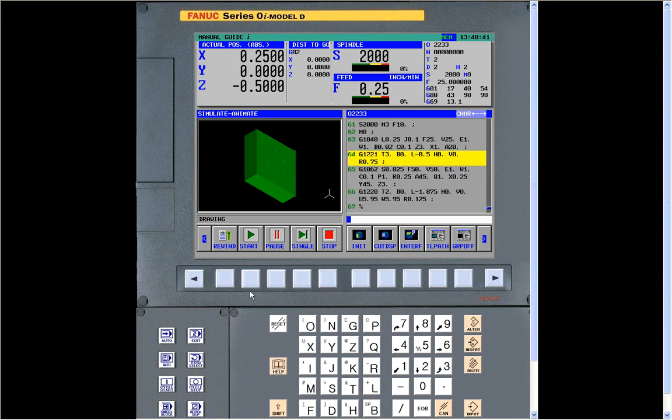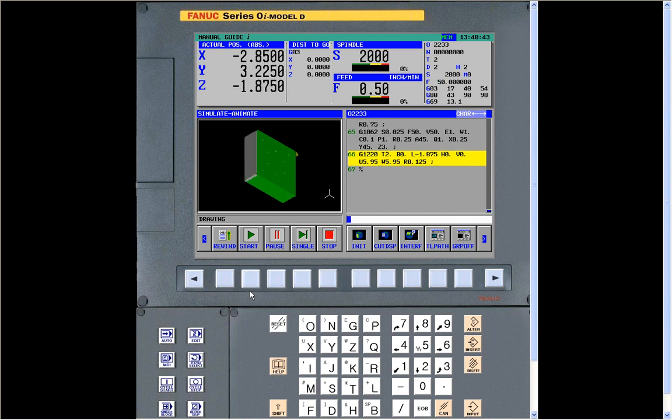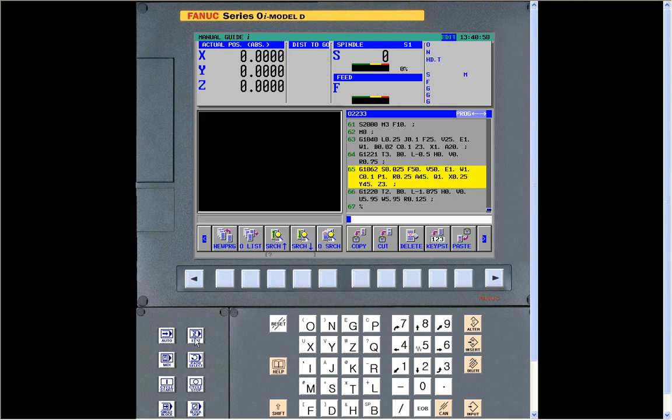You can see now it's doing the pocket in the middle. And it'll show the tool going all the way around the outside. And see how it shows these green lines here? That's showing where it's just barely cleaning up. So at that point, when we're getting our alarm at the end, we go group off, we go to edit.